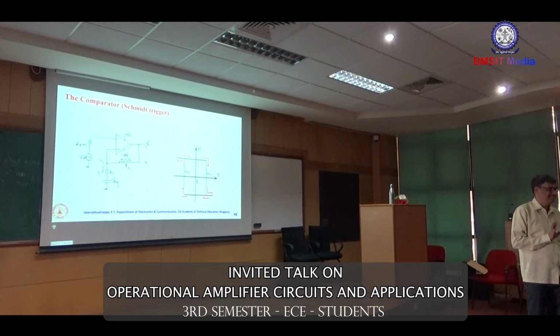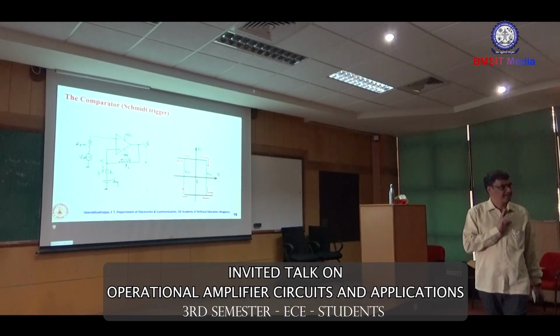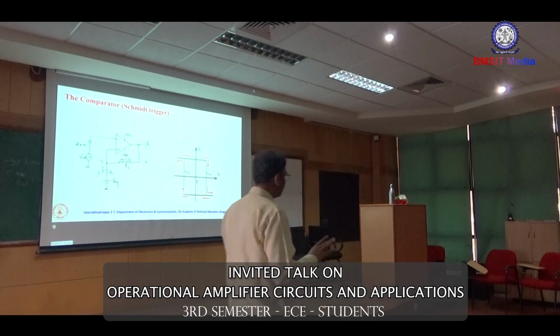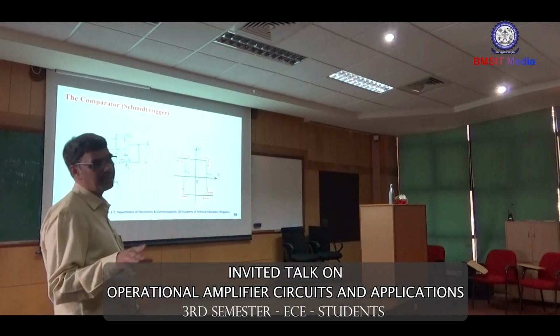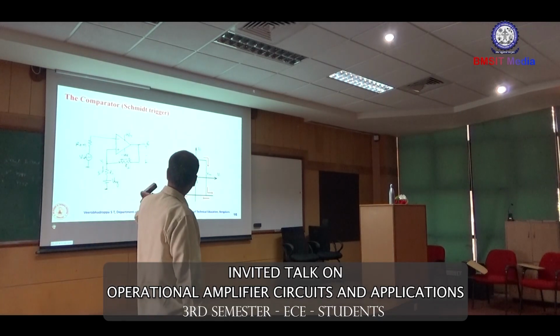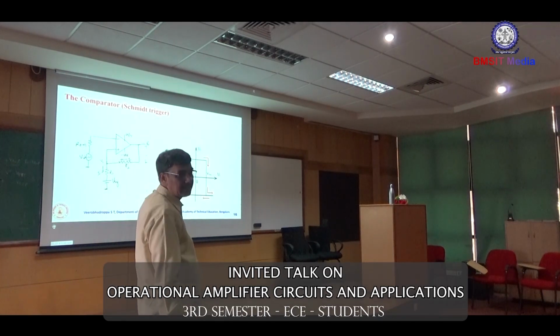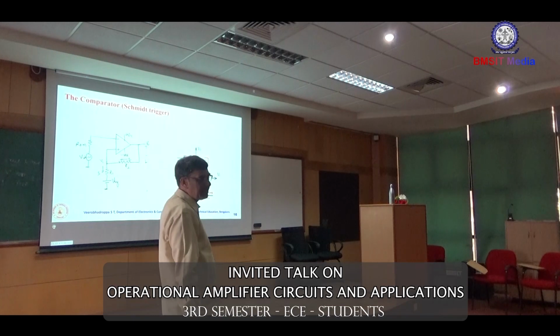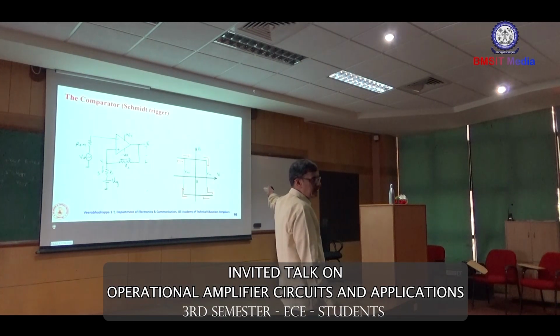You should remember, before conducting the experiments of any operational amplifier circuits, you should verify the zero crossing detector, not your voltage follower or anything else. Now in this Schmitt trigger, you are going to get these two threshold voltages verified by using this V reference. If you are applying a negative reference voltage, both are negative. When that V reference is positive, both the threshold voltages are positive.